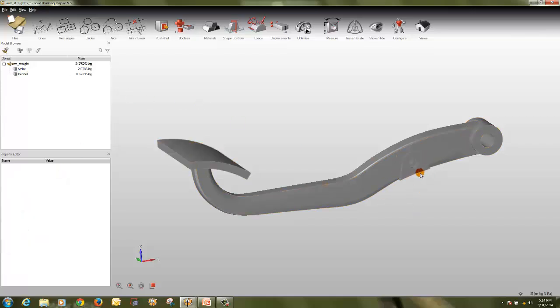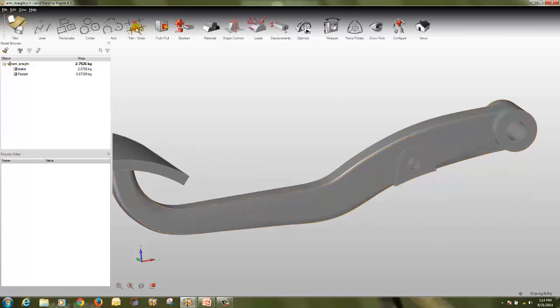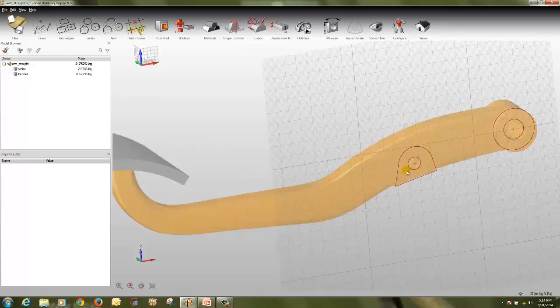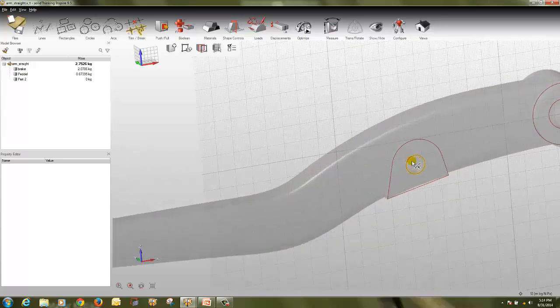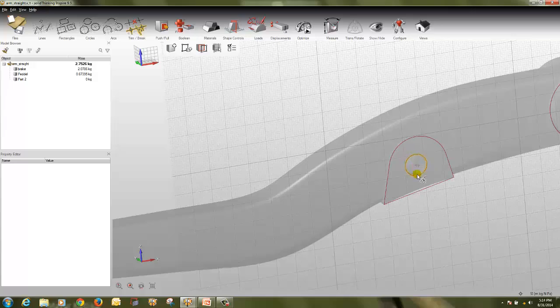Then this also will be a non-design space. So to create this, again go to break, select, create new part. But we don't want this to be the reference line. So what I will do is, I will right click on the edge and click on create curves. So I will select the curves which I want the surface to have like that.